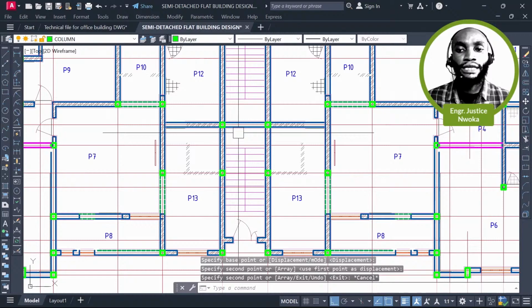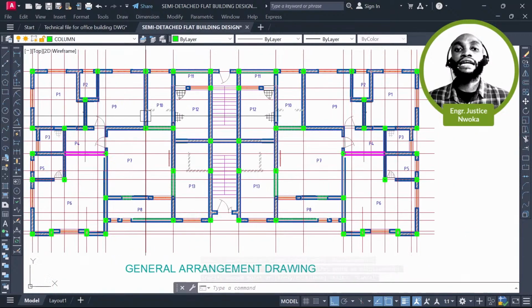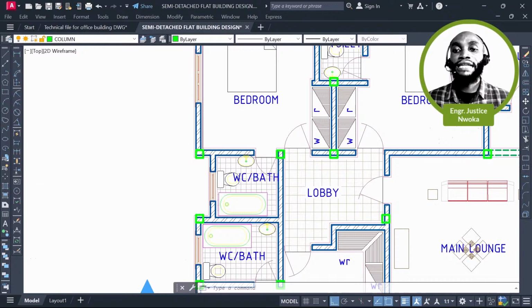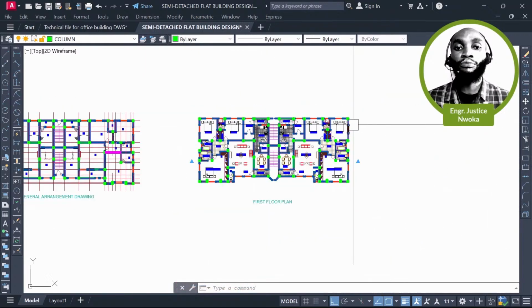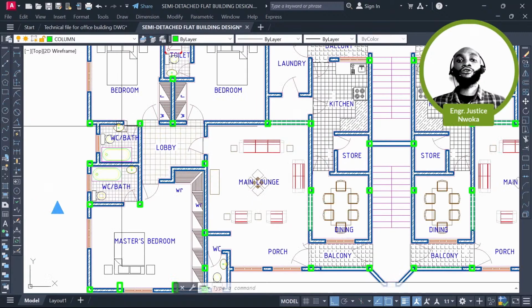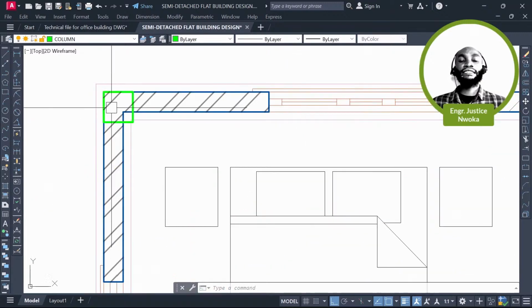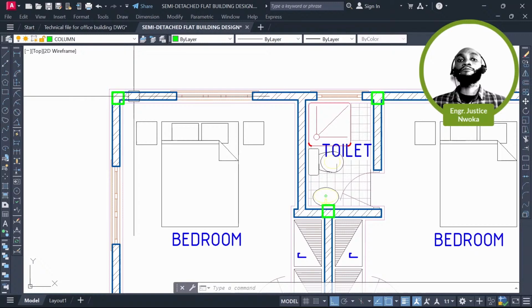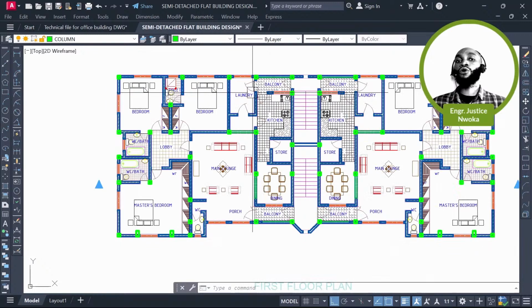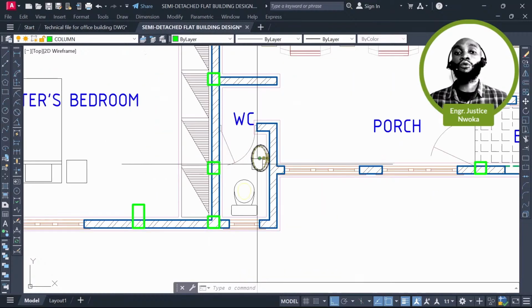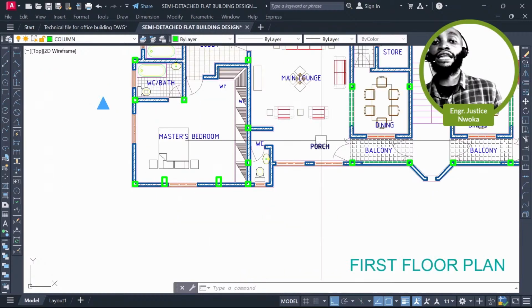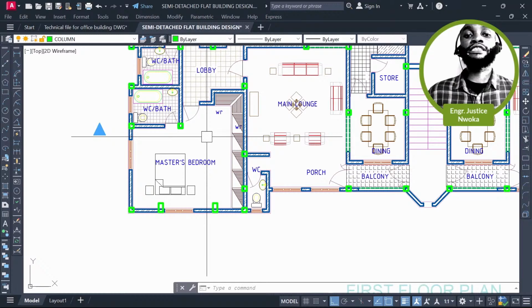So you can see that what happened there is that they used a 9 inches block wall on almost all of story 1, and that is for all the upper stories. They use a 9 inches block wall, which is basically causing our columns to come out.